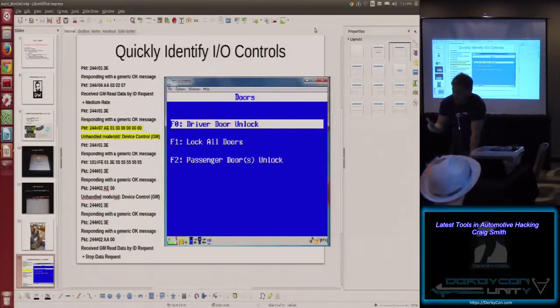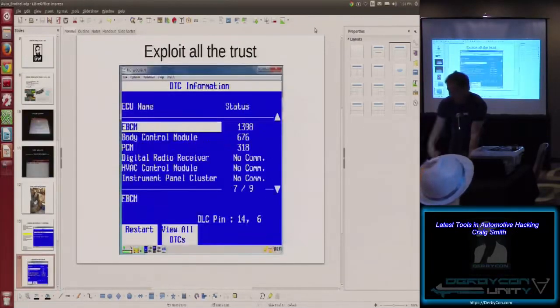So it's the packets that begin with AE are those I/O controls. And so the reason why it says unhandled is because there's nothing to do from a simulation perspective. And I'm not going to simulate a door unlocking with this because it's just software. I only basically simulate output, not input. So that's why you see it say unhandled, but you would know right away when you hit door unlock, that's the packet you can send to unlock that car door. You don't need the car there to do it. The nice thing is, as opposed to getting a rental of a target car and then figuring things out, you can just tell this the car you're interested in. And then as you press the buttons, here's what it would be for those cars. Which saves you a lot of time, so you're not looking through all that CAN traffic to figure it out.